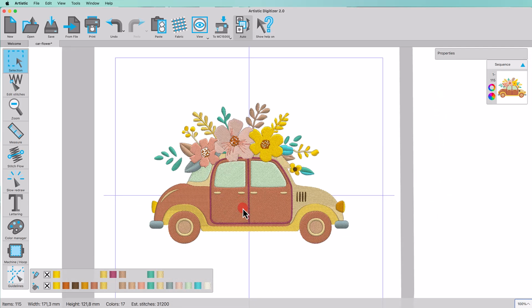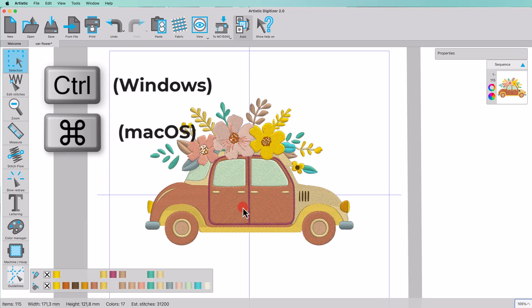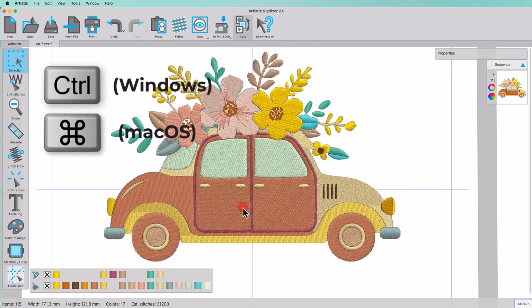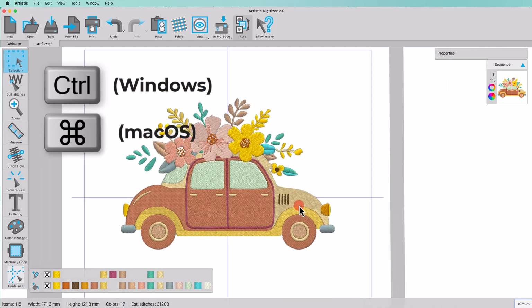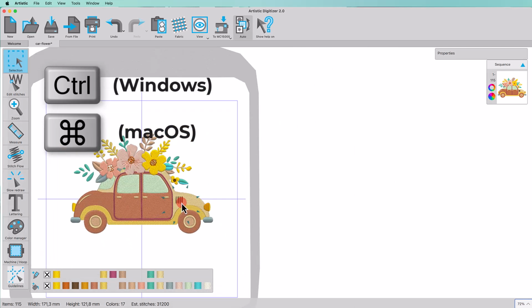In case you want to zoom in and zoom out using the mouse wheel, you need to hold the Control key down while moving the wheel so the wheel temporarily switches to zoom mode. If you scroll in, then you zoom in. If you scroll away, then you zoom out. Notice that the point where your mouse cursor is the zoom point.